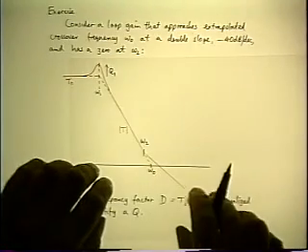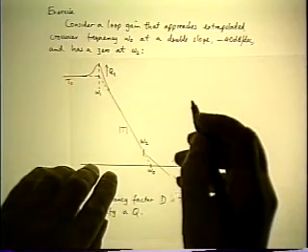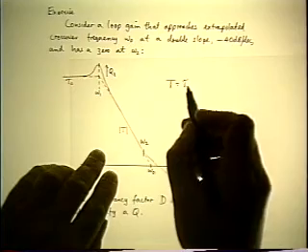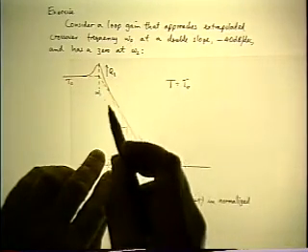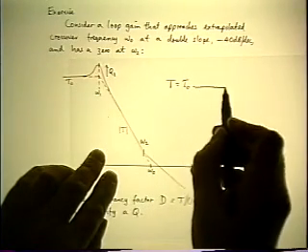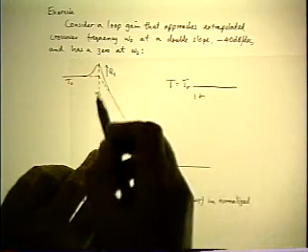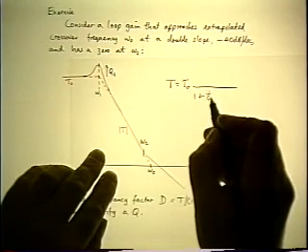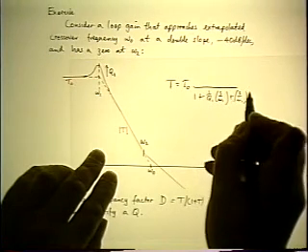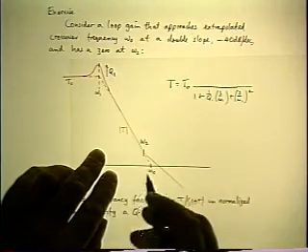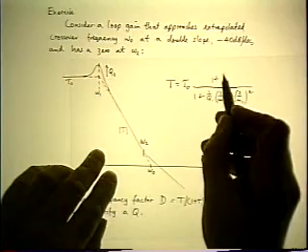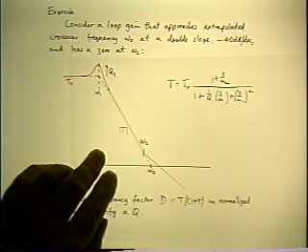Well, before you get too far along with that, let me start it off using the flat gain as reference, T equals T0. You look up in frequency and you see a concave downwards corner, which in this case is a double corner. So you represent that by the standard quadratic, and the parameters are already given. So its Q factor is 1 over Q1, s over omega 1 plus s over omega 1 squared. And you keep on looking up, and then there's a concave upwards corner at omega 2, so that's a normal zero. And that's everything.